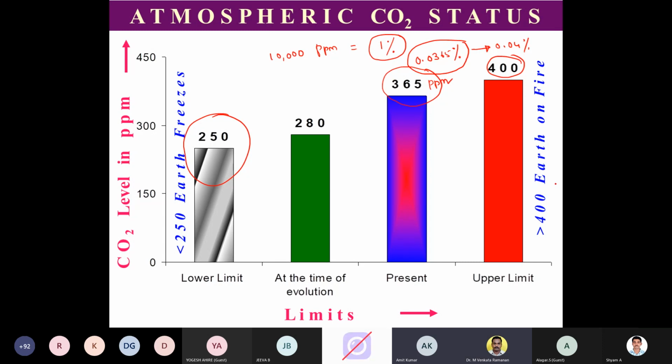As you would be aware, for doing stoichiometric analysis, we assume that air has only O2 and N2. O2 we take as 21% by volume or 23% by weight. N2 we take as 79% or 77%. This is by volume, this is by weight. We neglect the other gases. The other gases are argon, CO2 and H2O. These 5 things make up our atmospheric air, but we neglect these 3, saying that they are too low a value to be accounted for. Stoichiometry will never get affected by this analysis.